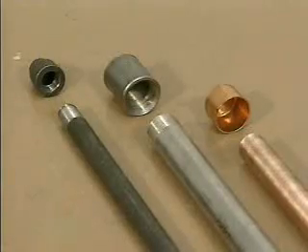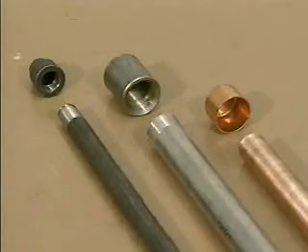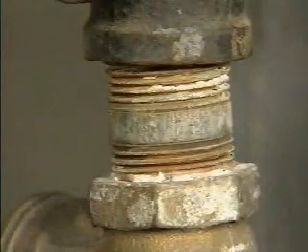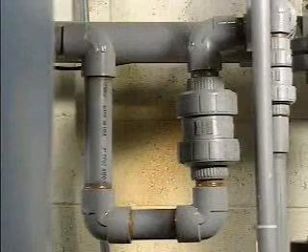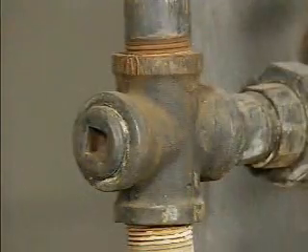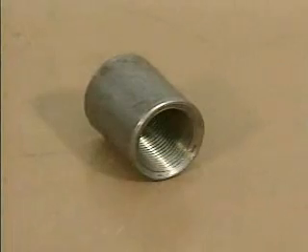Pipe fittings are generally the same nominal pipe size and material as the pipes to which they're connected. Fittings are typically designed to perform one of 5 functions. They can connect pipes and components. They can extend the length of a straight pipe run. They can change the direction of a pipe run. They provide branch connections. And they can close off the end of a pipe run. Let's see how various types of fittings perform these functions.